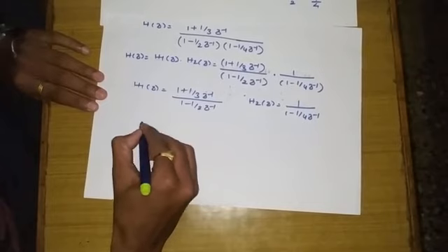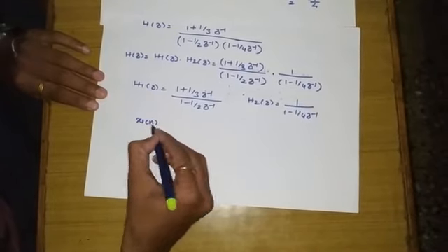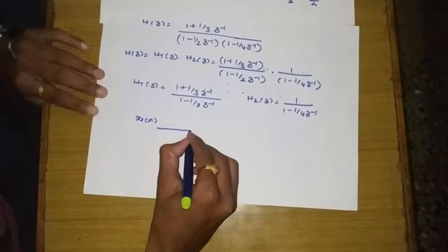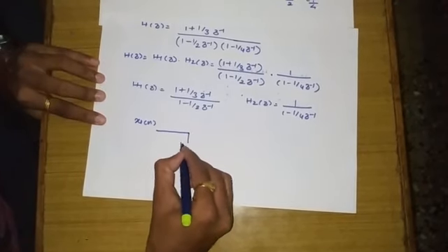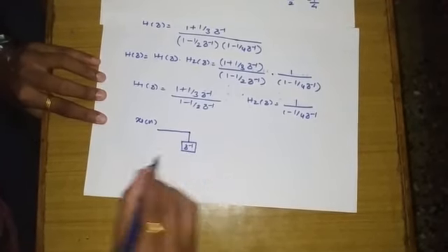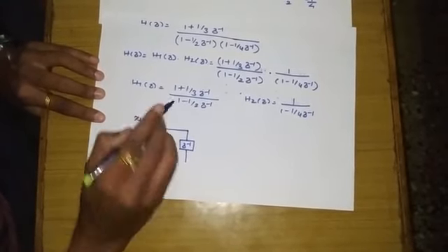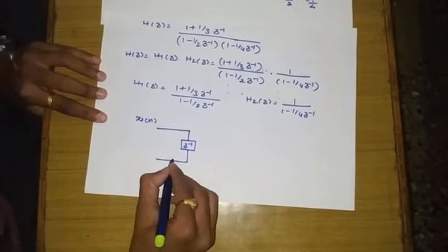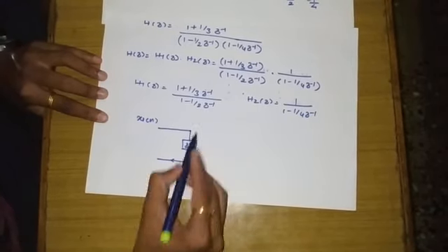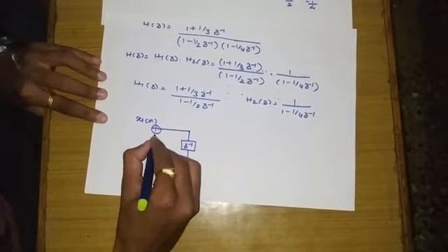So here it is, this is x1 of n as an input. You can see only one delay element is required, so we'll take this as Z inverse. Now in the denominator we have minus 1 by 2, so as per our rule, it becomes plus 1 by 2, with one adder. So it is placed here.